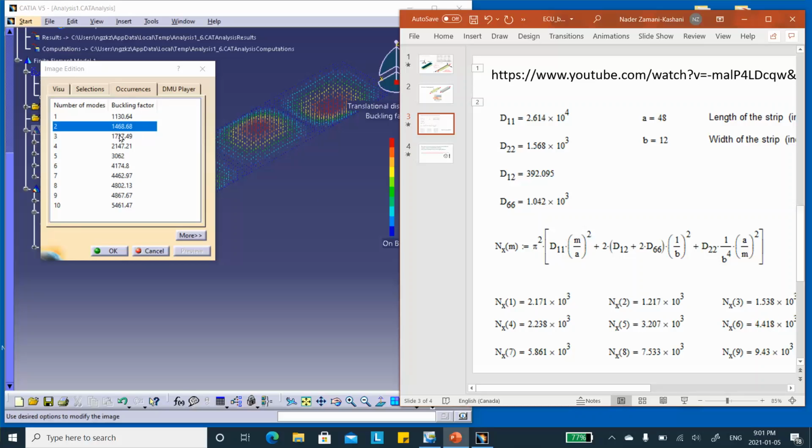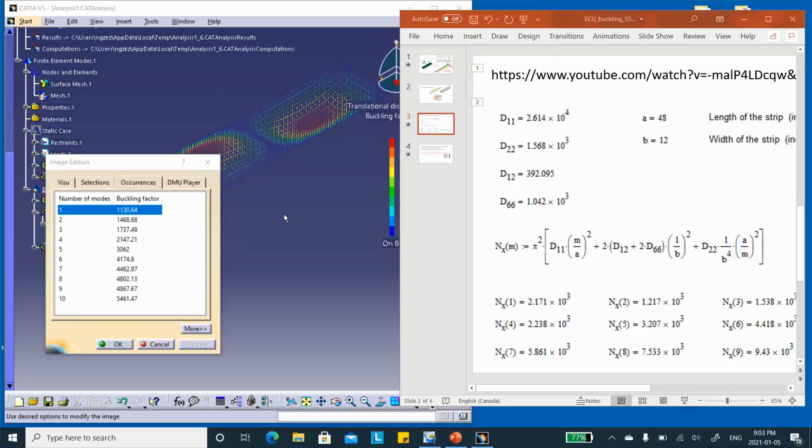If you go to the third one, what I'm going to do is, in the next video segment, I'm going to take this particular carbon epoxy lamina. I'm going to split it into two, so each one is going to have 0.125, and use it as a skin in order to take a core, a high density foam core, and cover the top and the bottom of the skin and calculate the buckling load.